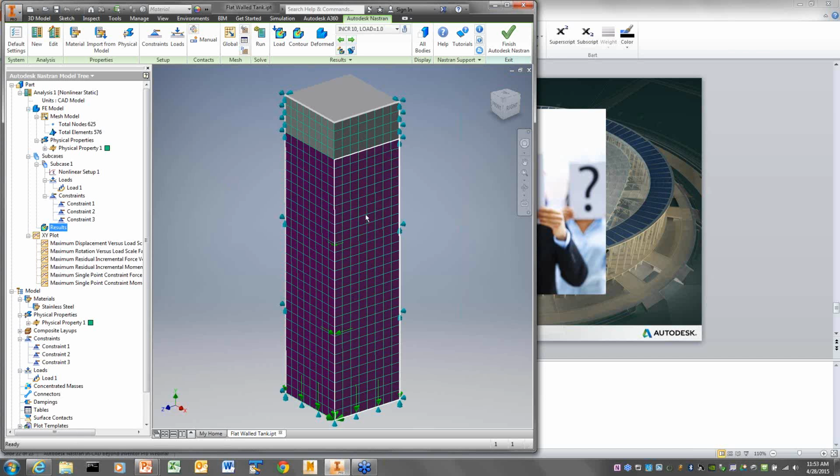When in fact, you have a lot of stress stiffening, and also once it deflects, it starts to bend and you end up with bending stiffness. This tank is sort of a subtle one because the tank actually moves and you're developing some bending stiffness because the tank sides do move out substantially, but the shear is still causing that big deflection of 8 inches that we saw. So sometimes the only way is to run it linear and run it nonlinear and see if there's a difference. If there's a difference, then it's a nonlinear problem.